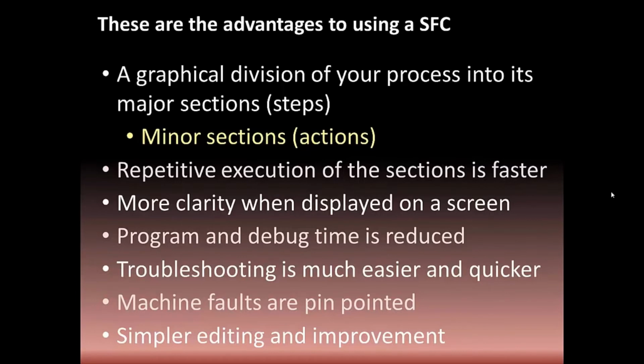So you can see that you have major sections, steps, and minor sections, actions, and each of these are graphical representations. Also, repetitive execution of the sections is faster because you're not executing all the code. Typically, in a ladder logic diagram, you put the most likely to be false instruction at the head or the front end of the rung.